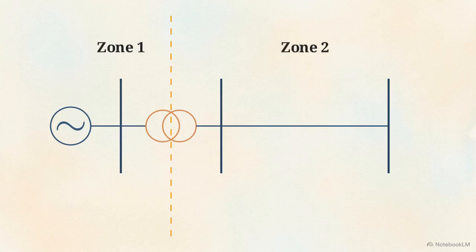Let's map this onto a standard 3-bus system, featuring a generator, a transformer, and a transmission line. Notice how the transformer cuts the system into two distinct voltage zones. Every calculation in this network relies on a fixed power anchor. We typically choose 100 MVA as our system S base, and that value remains unchanged even as you pass through transformer boundaries into new zones.